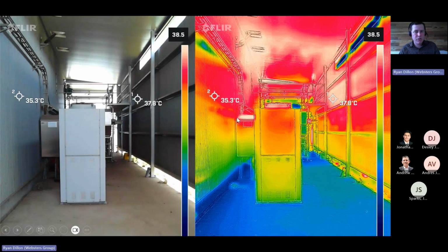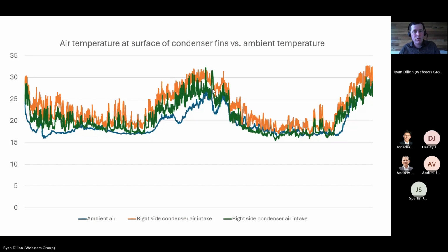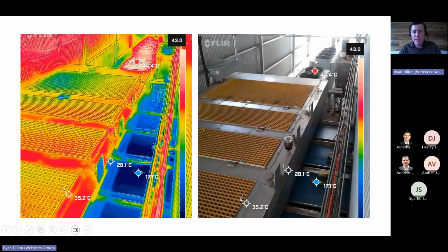But it doesn't necessarily stop there because the cold room's on the other side of this wall. So you have temperature gain through this building envelope concept we talked about with the $12 versus the $19 per square meter component of a cool shaded versus a hot wall with sunlight. This is the same concept where you've got a higher ambient temperature creating higher heat gains for the building envelope. Strangely enough, here's those chillers down here. In the same roof area, in the higher area where the heat rises to, there's actually a hole in the wall where conveyors go through.